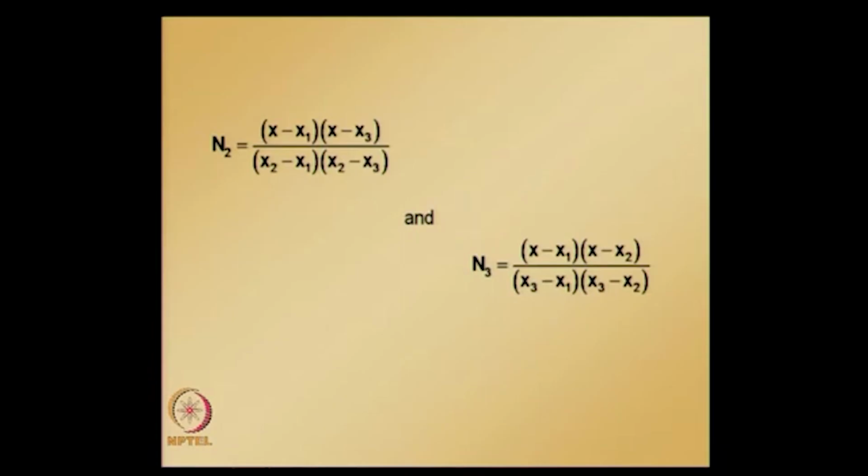So, these n1, n2, n3 are called shape functions for quadratic element. Notice that when compared to the linear element, the procedure or the effort of starting with a polynomial is very cumbersome. So, instead of going through this procedure, there is an alternative way, which is a Lagrange interpolation formula for shape functions.